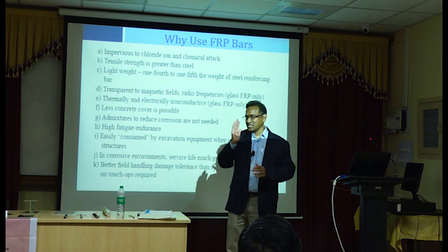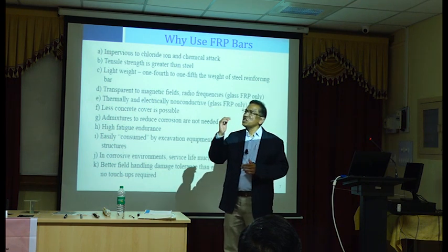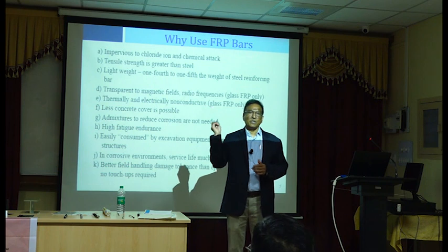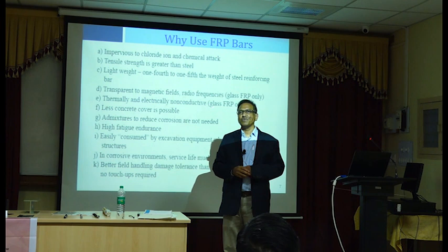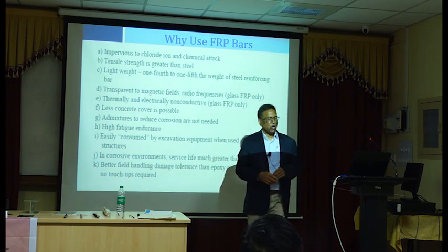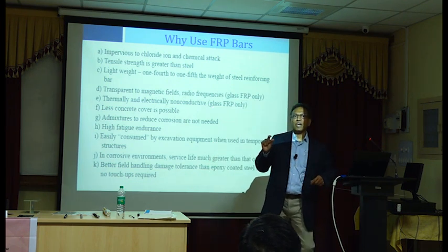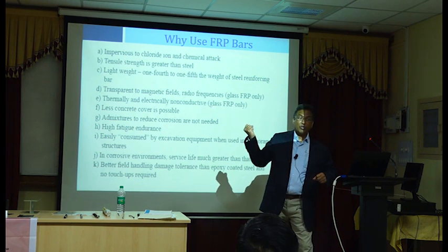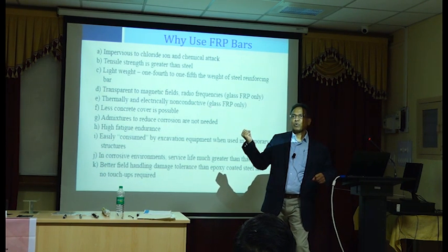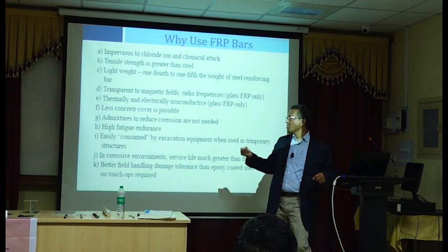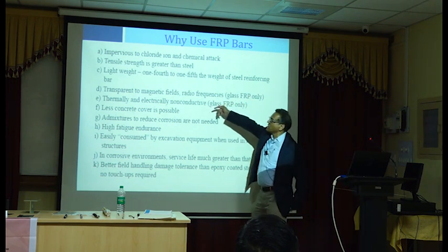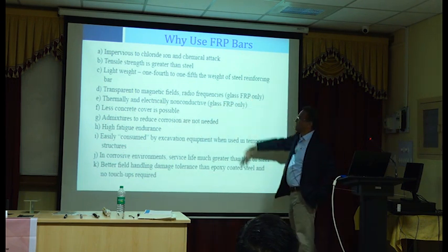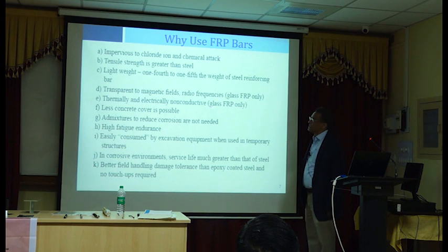So you just remember some minor things like this, because there's always pressure. Others will put pressure on you to use their product. They'll say, oh, we can reduce your concrete cover to 0 inch. No. You need a minimum amount of concrete cover to actually develop the bars, and therefore it's not okay to not have cover. But anyway, less concrete cover is possible, but it cannot be 0.